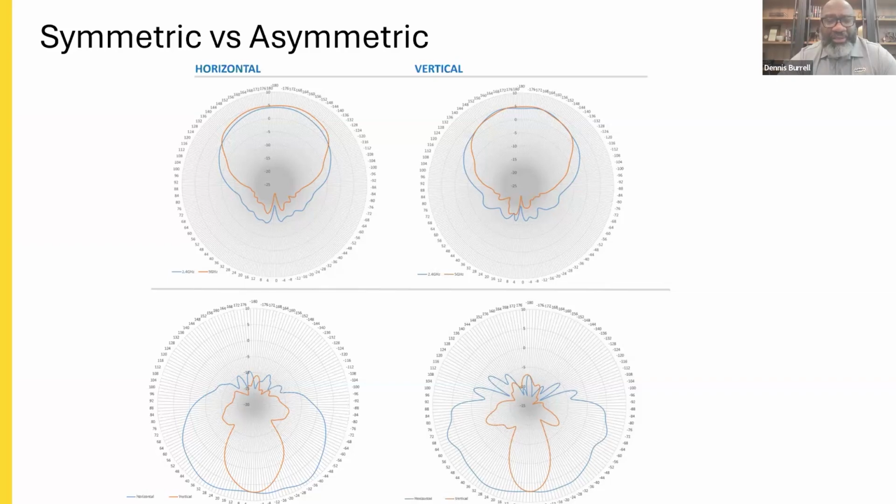Typically for some high density coverage, depending on if you're doing overhead or side to side. Overhead, you typically look at more of a symmetrical type of design for that spotlight area. And then on the side to side coverage, which is antennas on the handrail, you want more of a wider horizontal beam width because you want to cover more seats.